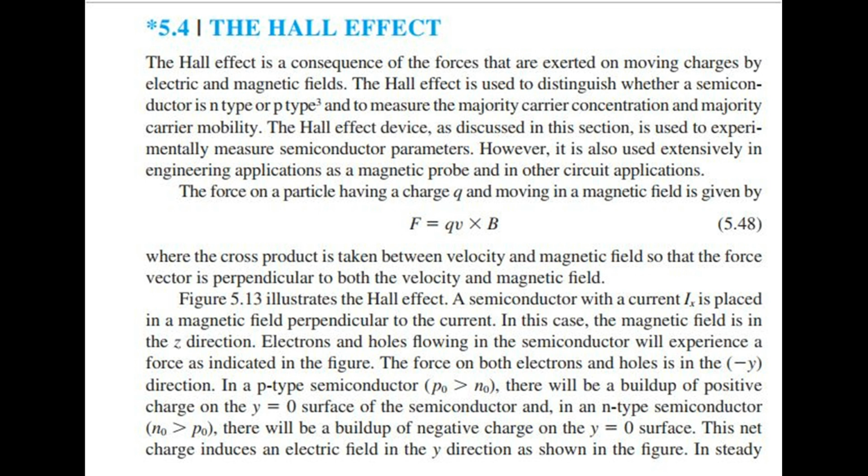The Hall effect. The Hall effect is a consequence of the forces that are exerted on moving charges by electric and magnetic fields. The Hall effect is used to distinguish whether a semiconductor is n-type or p-type and to measure the majority carrier concentration and majority carrier mobility. The Hall effect device, as discussed in this section, is used to experimentally measure semiconductor parameters. However, it is also used extensively in engineering applications as a magnetic probe and in other circuit applications.